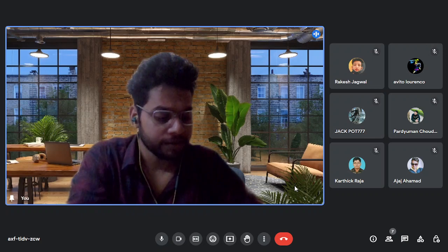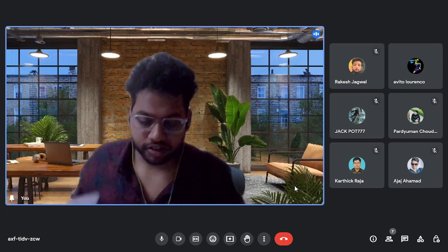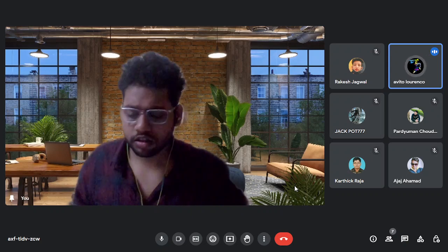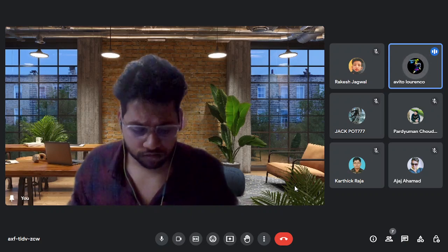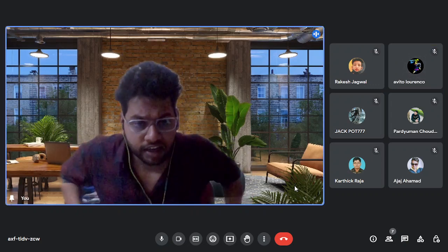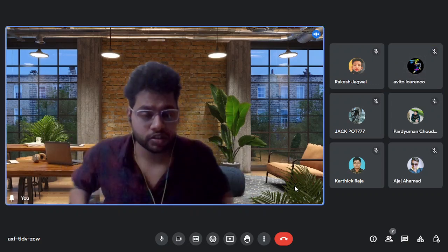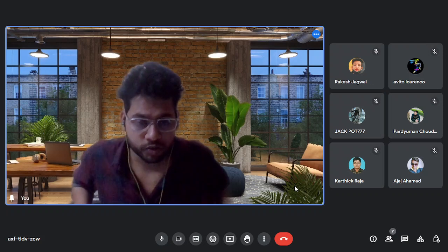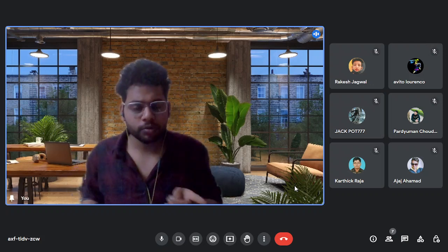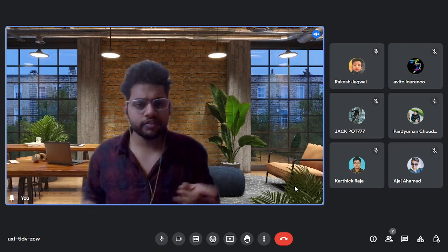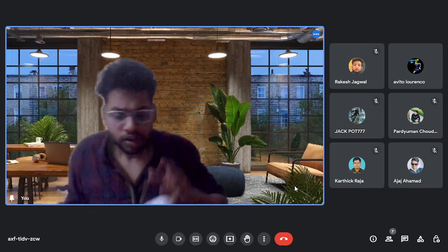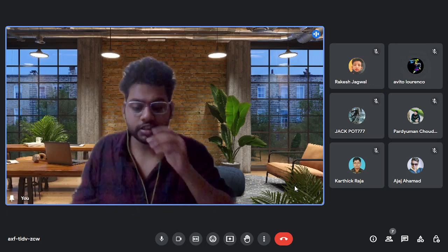So coming to the next question, just to keep it as per the interview, the answer is that the capacitor is used to help compensate for the large initial starting torque required. But here we have an auxiliary component, the centrifugal switch. The centrifugal switch gets turned off when the starting torque of this single phase induction motor rotor becomes constant. Okay, now coming to the three phase induction motor.